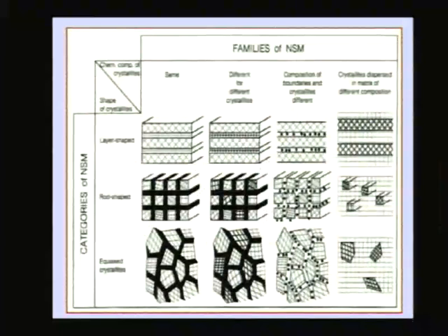So such sophisticated techniques are available to see the structure and also get to know what is the atomic distribution, what is the composition of such a grain boundary, using techniques such as atom probe field ion microscopy, APFIM people call it, or 3-dimensional atom probe, 3D AP people usually refer to it as. Such techniques can be used to find out the composition and structure. Structure can be obtained from high resolution electron microscopy, as I mentioned, and one can get the properties using techniques such as nano indentation. So these are some of the techniques which can give you an idea of the properties.